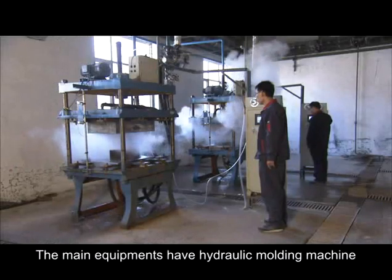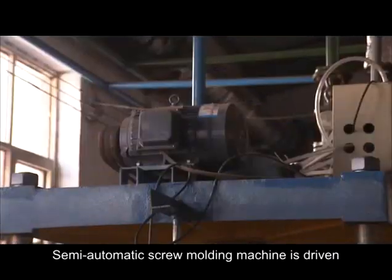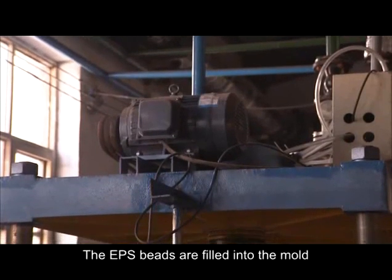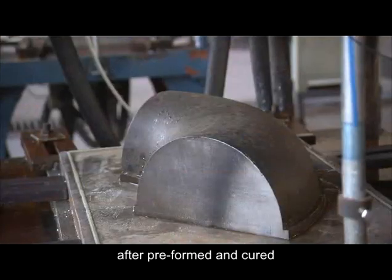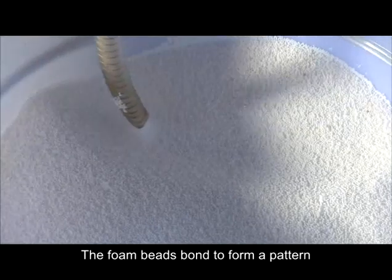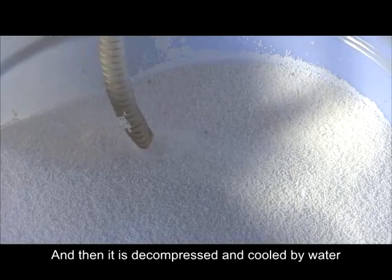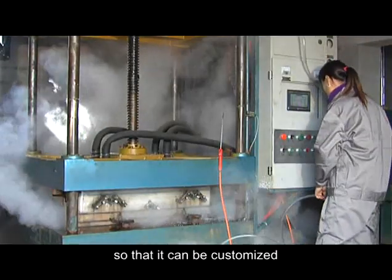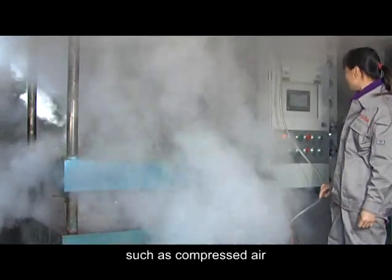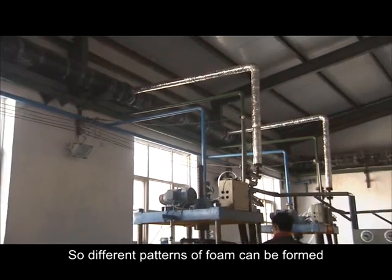The main equipment are the hydraulic molding machine and the semi-automatic screw molding machine. Semi-automatic screw molding machine is driven by an electrical machine. The EPS beads are filled into the mold after preformed and cured. The foam beads bond to form a pattern through steam heating and pressure effect, and then it is decompressed and cooled by water so that it can be set. We should open the mold by some steps, such as compressed air. At last, different patterns of foam can be formed.